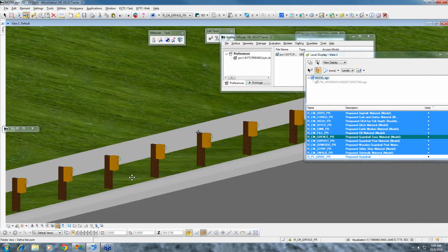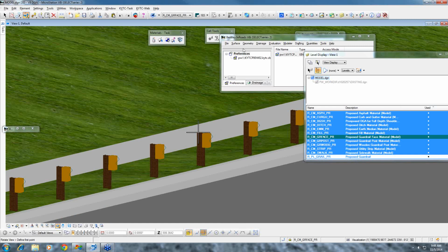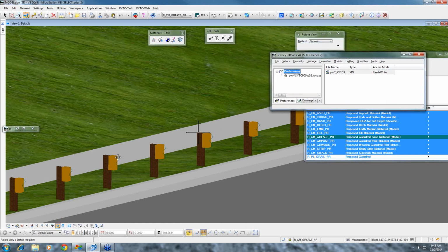It'll want a line to go off of, and I guess the question is, can you use that line that you've got laying on the ground that represents the face of the guardrail post? Oh, yeah. Can you use that feature? Well, you'd have to offset that feature up to your proper height. Right. But yeah, you could do it that way if you wanted to. Yeah, you can offset that up and extrude. So yeah, multiple ways, just like most Bentley products, multiple ways of doing stuff.